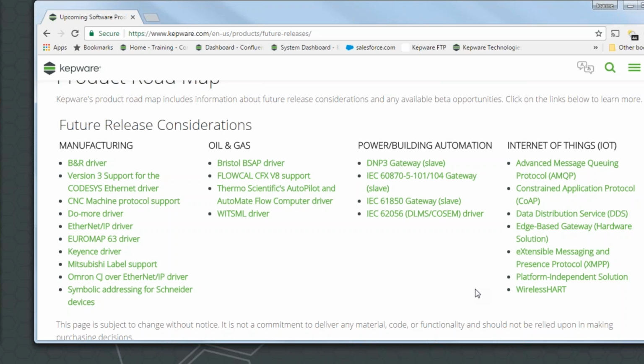So if I'm frequently changing which tags I'm reading, and I'm using what's called dynamic addressing, where I might read this tag one day because I'm running X recipe, and then that changes because now I'm running Y recipe, so now I'm reading a different set of data. Can I on the fly change those tags dynamically and have them added to a schedule?